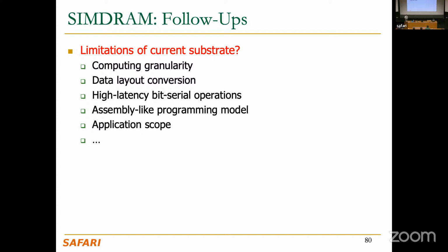I didn't highlight much here, but when I'm doing this type of operation, I'm changing the paradigm. When I do computation on horizontal data, I'm doing operations in a bit-parallel manner, right? So the latency does not necessarily depend on the bit precision. Of course, it creates some delay on the circuitry, but it does not necessarily scale with the bit precision of the computation. Over here, I'm doing a computation bit by bit in a bit-serial manner. So it means that doing a 16-bit addition is going to take twice the time of doing an 8-bit addition.